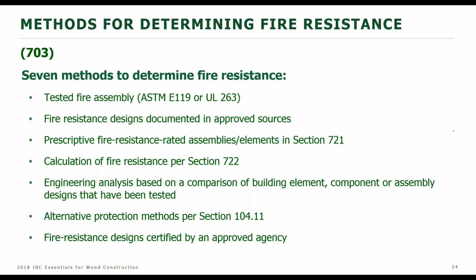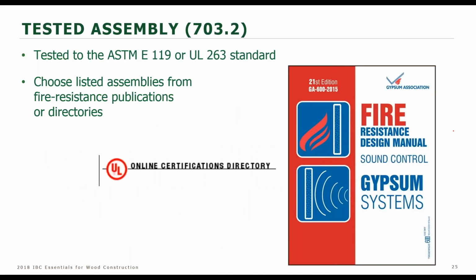They're listed here. I'll mention a little bit about each. The testing itself for any particular building assembly, this is very common. Most of you are aware of this. You choose a tested assembly out of the fire resistance directory of one of the test laboratories, such as UL or the Gypsum Association. I think we're all familiar with that.